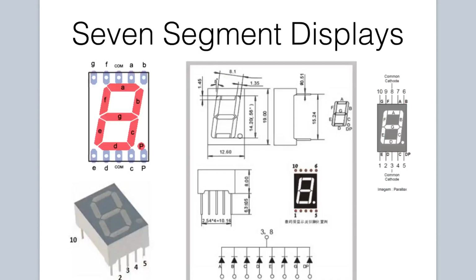Let's first address how 7-segment displays work. If you look at the schematic for a 7-segment display, you will see that each segment or individual piece that has to light up to display a part of the final result has a letter and a corresponding pin that is associated with it.